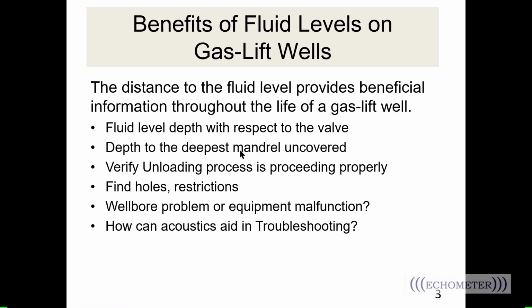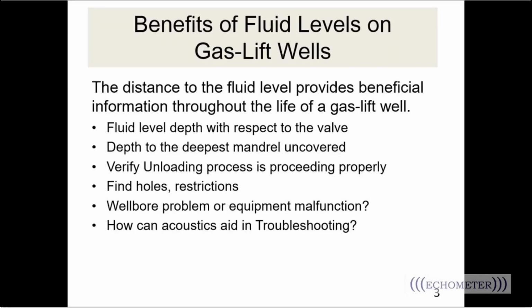We see the depth to the deepest mandrel uncovered. You can verify if your unloading process is proceeding properly, find holes and restrictions. We can use the acoustics to determine if you've got a wellbore problem or maybe an equipment malfunction. And we're going to look at several examples of how you can use acoustics to aid in your troubleshooting.